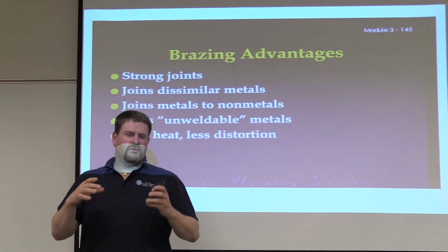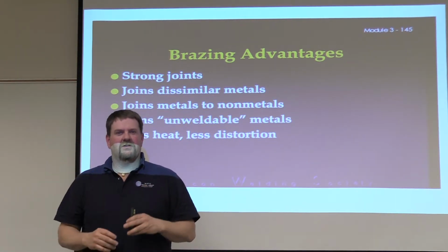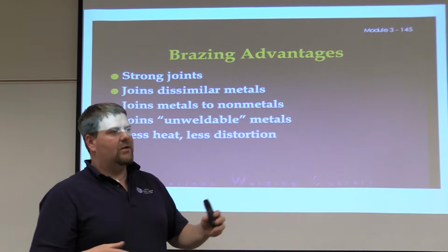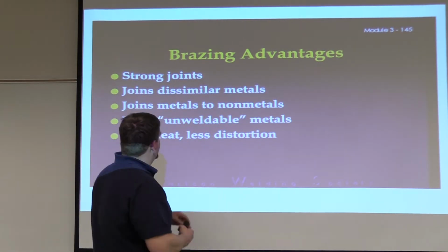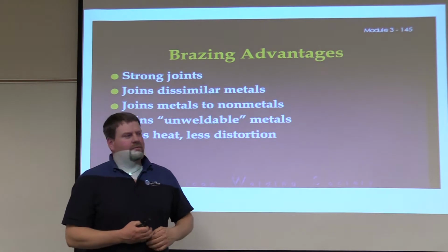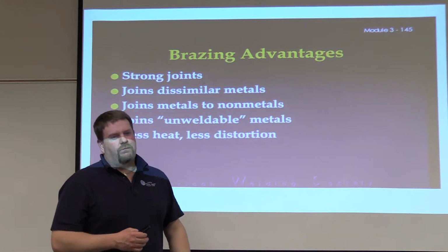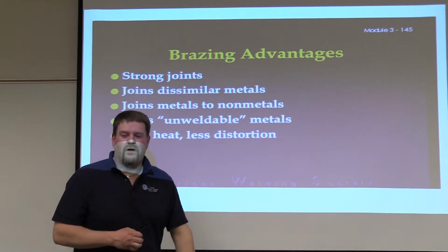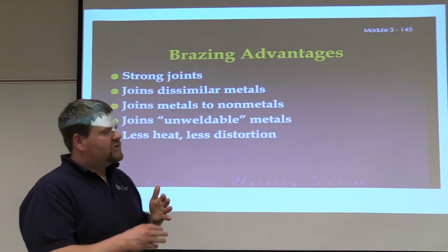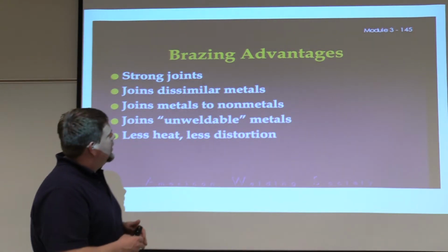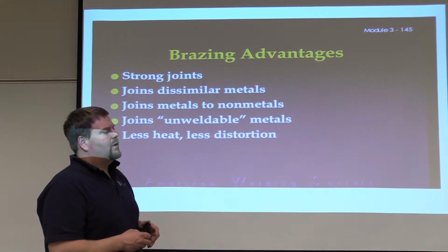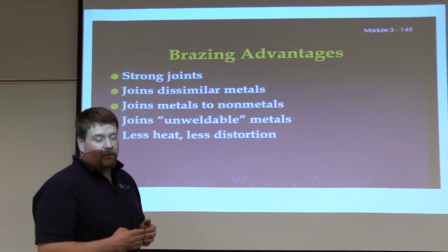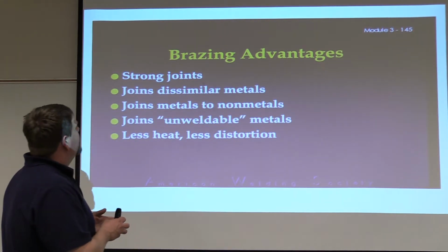So you don't want to blow a hole in the middle of a stainless steel pipe, but you need to fix a leak or something on it. You can put a saddle around it or a piece of steel, get it fixed up until you can contain the leak and replace that piece of material. I can't tell you, being an ex-HVAC tech and plumber, I brazed and soldered a lot of pipe and a lot of material. I've also welded a lot of radiators and fixed simple things, heat exchangers, stuff like that in large buildings that most people couldn't do or they were scared to do, and so forth. I have saved companies a lot of money by being able to braze. It's a very important skill to have. And a lot of downtime too.